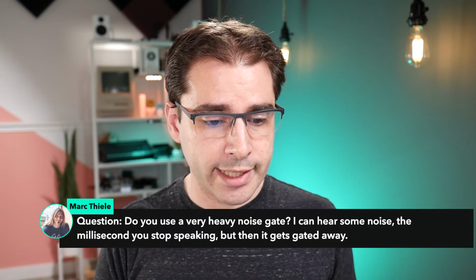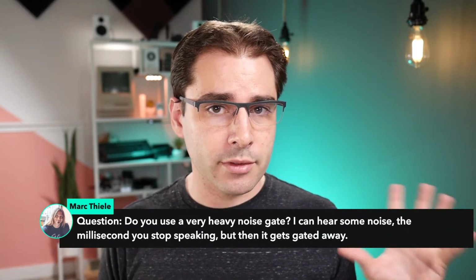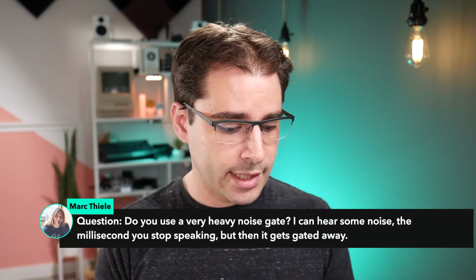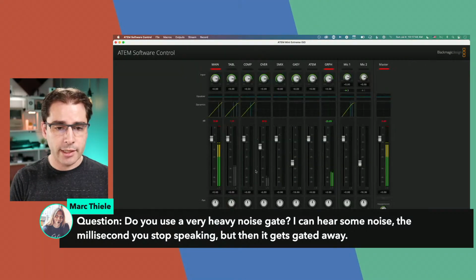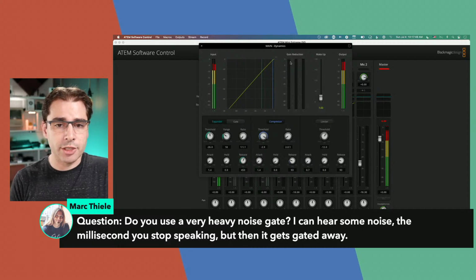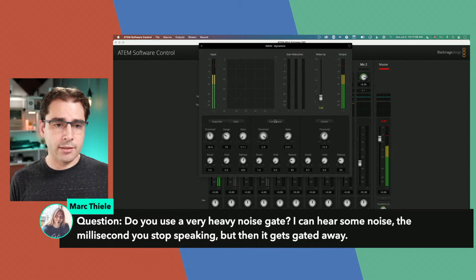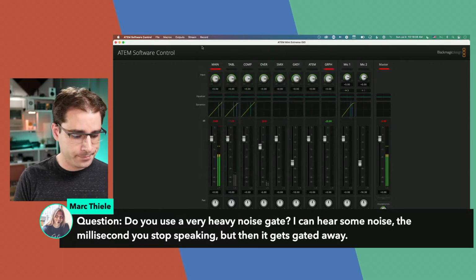Do you use a very heavy noise gate? I can hear some noise the millisecond you stop speaking, but then it gets gated away. Yeah, there's a couple of fans in here, so there's a little bit of noise. And I do have a noise gate on it, and it looks like this. You can see the gain reduction: if I stop talking, it's going to clamp back down, and that gets rid of the little noise. If I turn these off, you'll hear it. So now this is just the noise of the room. It's not too bad, but I do prefer it with the expander and compressor on it.